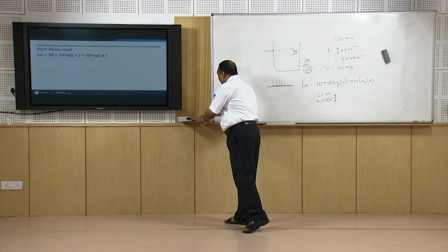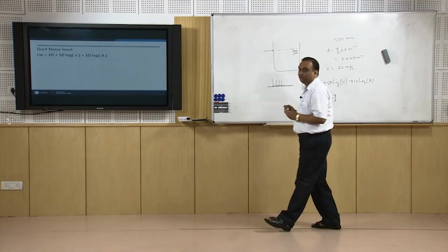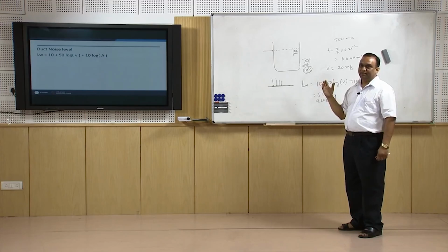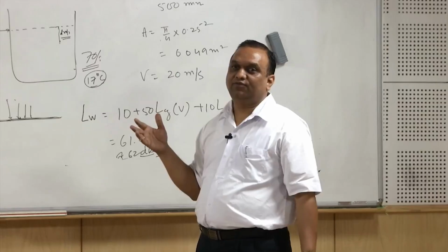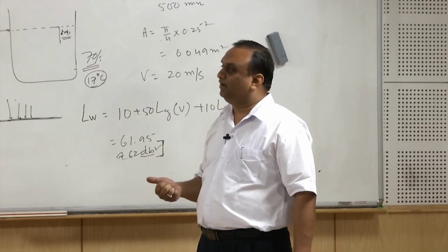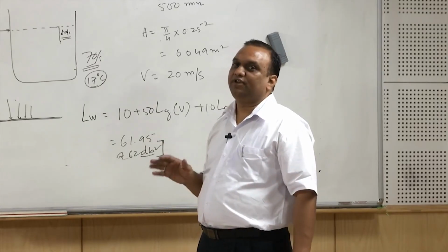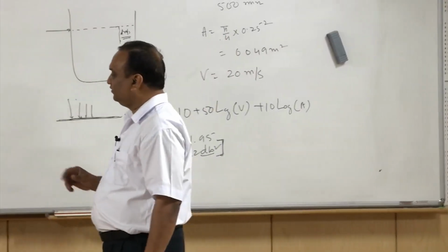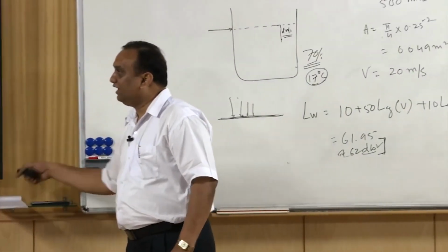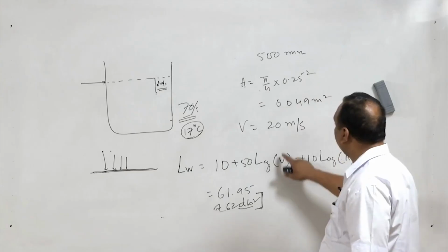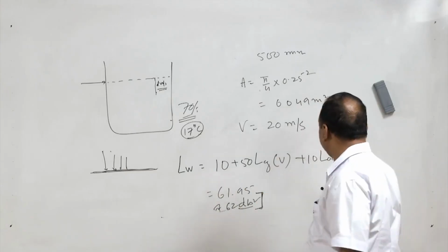So this much sound shall be created, because if the sound level in a duct is high, in that case you may feel comfortable thermally, but otherwise you will not be comfortable in that occupancy where the noise level is very high. So noise is one of the criteria for designing the size of the duct, because if we increase the velocity, noise level will increase.